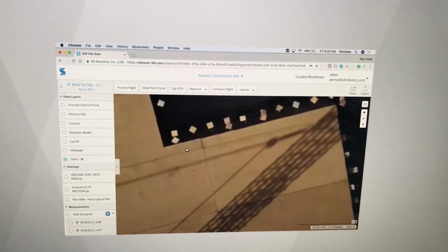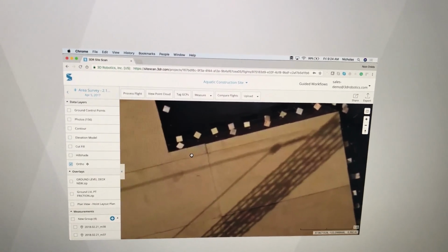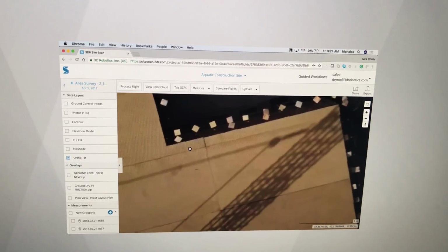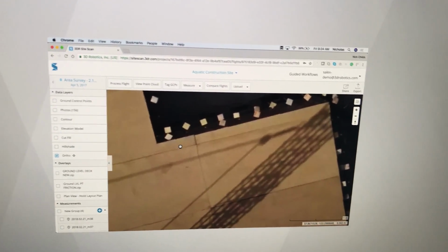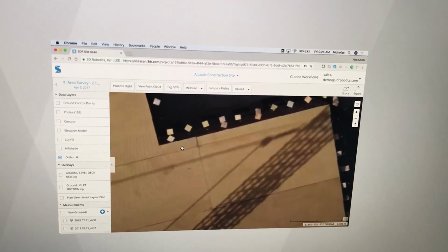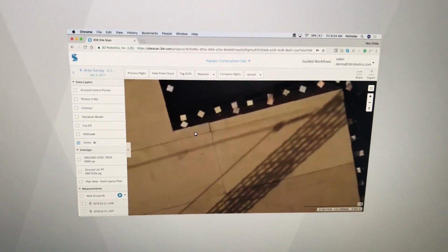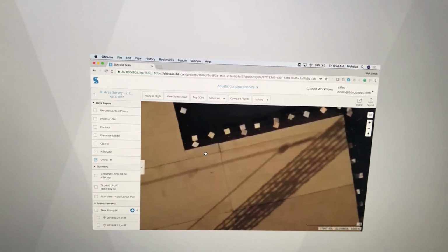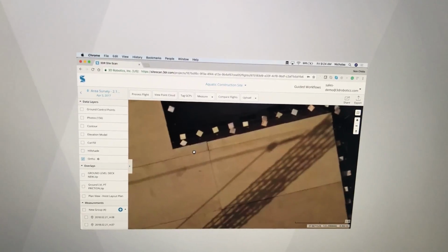And I had to take 3 days going in with Pix4D and editing out all that noise. And when you make a mosaic of that, it gets fuzzy edges of the buildings and stuff. And I had to go in and use Mosaic Editor to choose the nadir shots for the edges of the buildings to make sure that they all look good.